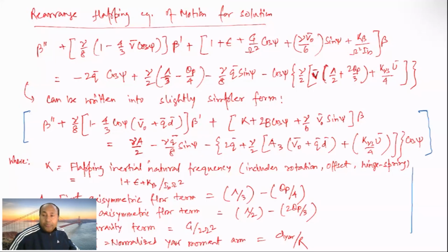Welcome back. So we'll now continue the discussion on this full flapping equation. What we finally derived in the last session is the complete flapping equation of motion, including all the forced effects: effects due to aerodynamic forces and moments, and yaw effect. So this is the forced motion flapping equation.